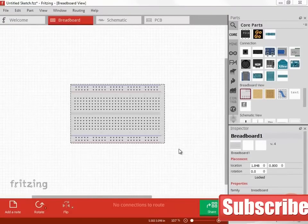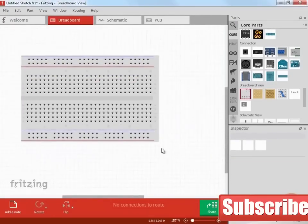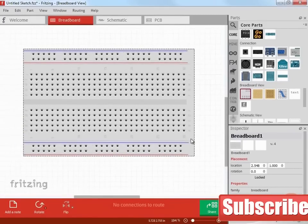The spacing of the contact points is typically 0.1 inches or 2.54 millimeters. This allows for easy insertion of ICs of the same pin spacing. Other components can be inserted easily. With a few jumpers, complete circuits can be built up quickly. It is important to understand how the contact points are connected.